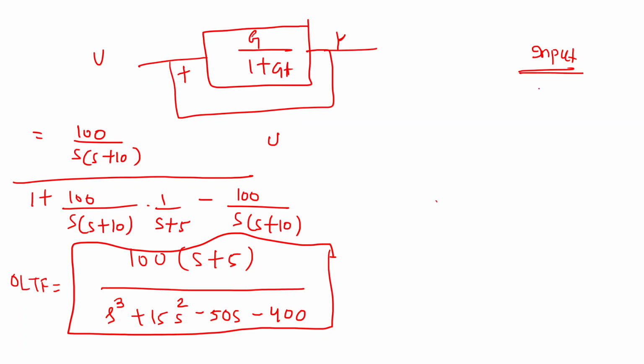First of all, we are not taking the impulse input, because for the impulse input the amplitude is infinity, so we are not considering it because it is not a bounded system. As the input is not bounded, the output is also not bounded. That's why we do impulse input for the transient analysis, but for steady state error you don't consider the impulse input. So the other three inputs I have to take. What is the first input? Step input. The second input is the ramp input. The third input is the parabolic input. So these are the three types of input.